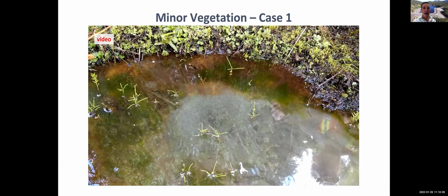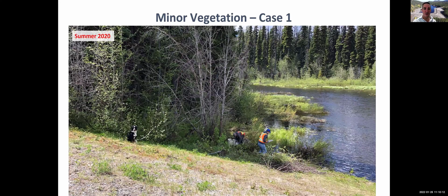So hats off to the operator in this situation. I'm going to show you the line at which the vegetation was, but that's me in the blue hat there. And that's the operator, one of the representatives for the dam, and he's helping me install some monitoring equipment. But where I'm standing there was probably 10 to 15 feet of brush, and it extended back. You can see some of it is all hacked down and laid down. So for him to find this, he would have had to be certainly ankle deep in water. And this is typically what it does require to inspect these dams.